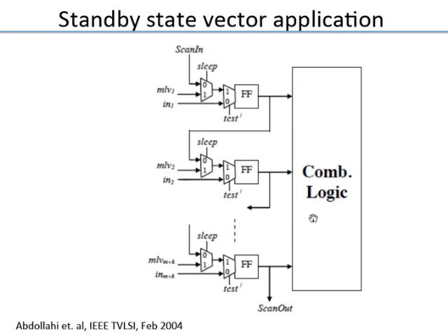So you have to analyze your combinational logic, because it will have a lot of gates deep inside, all the way down. A gate closer to the inputs, you can easily control because its inputs come directly from the flop. But for gates deep inside, even though you know which bit pattern at the inputs will give the lowest leakage, it might be hard to get to that pattern because there are a lot of constraints. You try to get that, but some other gate will get a different bit pattern which will be higher, and so on. So there is this problem.